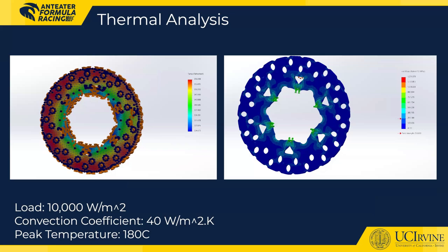However, this high stress is likely unrealistic due to the boundary conditions which prevent the brake from expanding. In reality, the brakes are clamped and not fixed, so these stresses would not be as high.